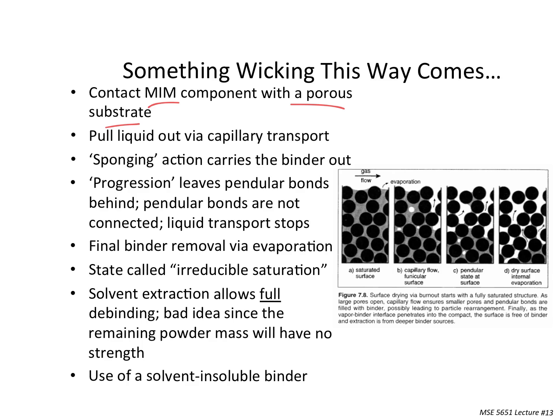That alumina contacts the surface of the part, and as it heats up or is exposed to a solvent, that liquid can be wicked out into the surrounding alumina particles. So again, we're using capillary forces for good in this context, and they transfer liquid from one solid to another solid that we care less about.